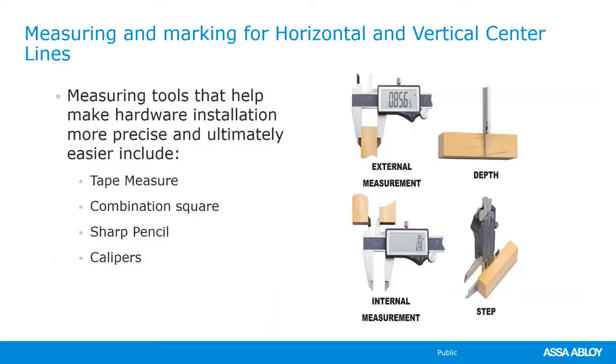Now, as I mentioned, I'm a big fan of using calipers, and some of you on this training may have never even seen calipers before, but they're very, very multifaceted. They work for several different things. As you see here, we can do an external measurement just to see how thick something is. Well, this may be necessary if we lost instructions and we're trying to see what size the screw is, and we need to drill and tap a hole in a door for a particular installation screw. Well, we can use these calipers to measure that screw diameter very accurately so that we can get the right drill bit. You can look at internal measurements,